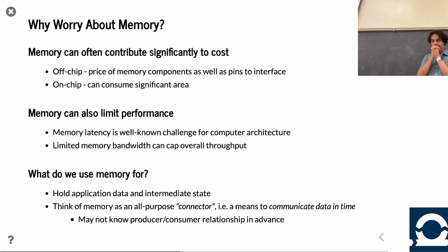And here's one interesting way to think about memory, which I think is widely appreciated. Think about memory as a connector. In this course, we've been thinking a lot about hardware designs. You see me draw schematics that look like graphs: this gate attached to this gate, or this component attached to this component. You write your Chisel, instantiating these components and connecting them together. So that connectivity is very static. Memory allows for much more dynamic connections, right? You can write something to a memory location in one cycle, and something else later on can go read that data. In a way, the thing that produced it and the thing that consumed it communicated, but rather than having a direct wired connection, they instead wrote to memory and read it back from memory, right?